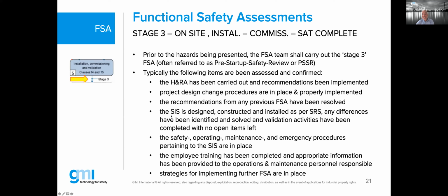That the SIS is designed, constructed, and installed as per SRS. Any differences have been identified and solved, and validation activities have been completed with no open items left. Again, very simple story. No open items left. If it has been tested during the site acceptance test and there were some comments, we want to see that closed before we give the allowance to go online with your hazards in your factory.